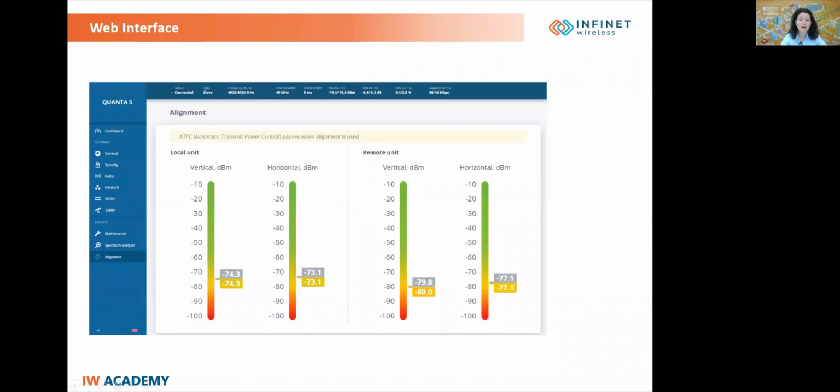The graphical antenna alignment tool allows you to visualize the signal characteristics on both sides of the link in order to make the antenna alignment process more accurate and easier. It helps to find the best antenna position by comparing the actual received signal level with the calculated reference value. When the measured signal level is close to the reference value, the square indicating the signal level becomes green and shows you that the alignment is proper. Now that the signal level is yellow, the alignment is not proper.